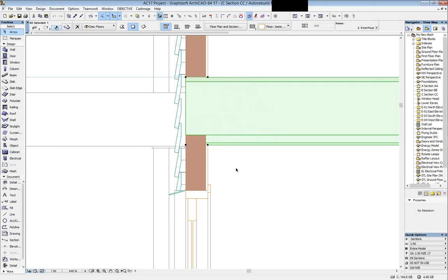Now, I know that another thing what we're trying to do is create drawings that convey what we're trying to achieve. We want drawings that are clear for the building inspector, for the builder. So of course we can add all that information. Now we can do it via modeling, or we can do it via 2D overlays. If you want to do it via modeling, you could use complex profiles, and into a complex wall profile you could add your top plates and your bottom plates and your nogs and all your insulation. If you didn't want to use that, you could use CADimage wall frame tool, which automatically places all your wall frames to 3604.